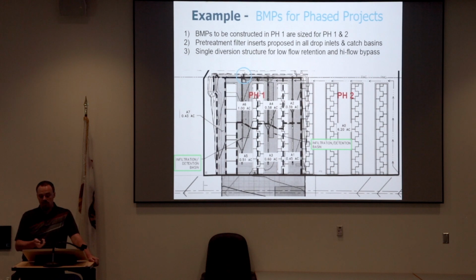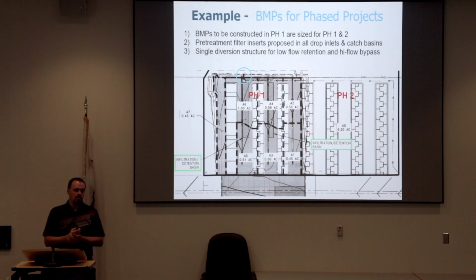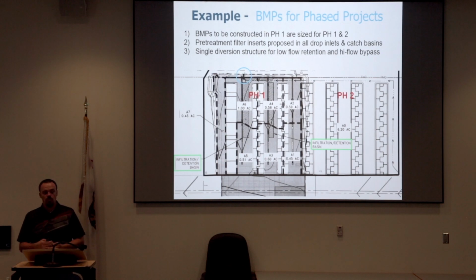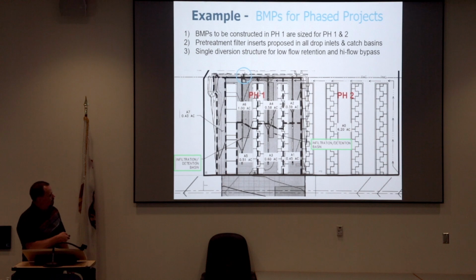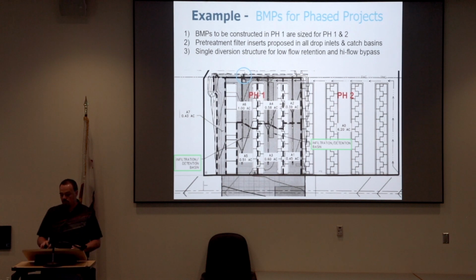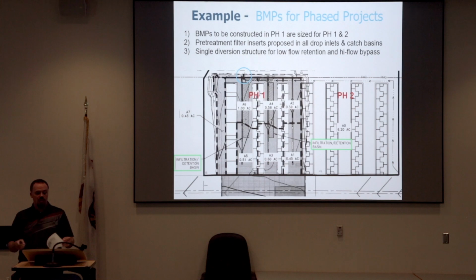And BMPs, in this case, they chose to do subsurface infiltration with proprietary infiltration devices. So you don't lose any of the surface availability, so you still have it under the drive aisles. They have access hatches as well, for maintenance. And then they created an artificial high point at the bottom of the development, which is right here, to make sure that everything drains this way to their area, so they don't have anything this way that they have to treat with a second BMP. So this is a good example of, at the surface level, an excellent design.